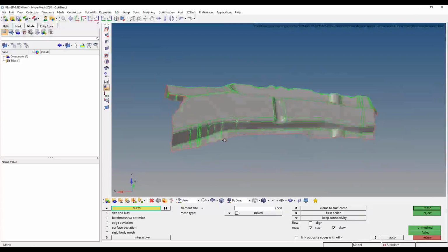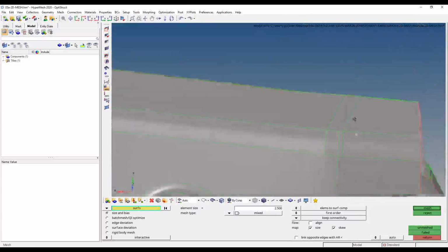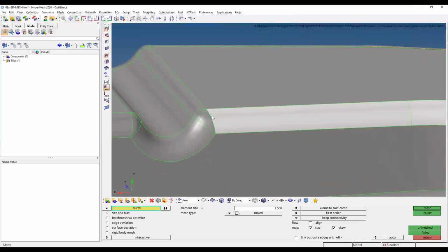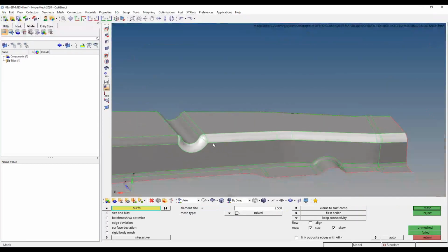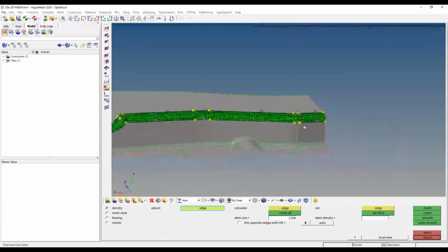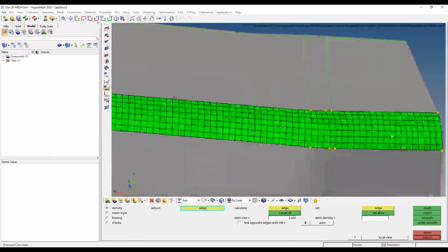So I would not recommend going about that. But instead, one thing I like to do is take a handful of surfaces at a time and maybe mesh a dozen or even half a dozen just at a time here. So right now I've only selected about half of that top fillet, that 17mm fillet on this side. I'm just going to mesh that. And now I'm just going to come in here for a quick review.